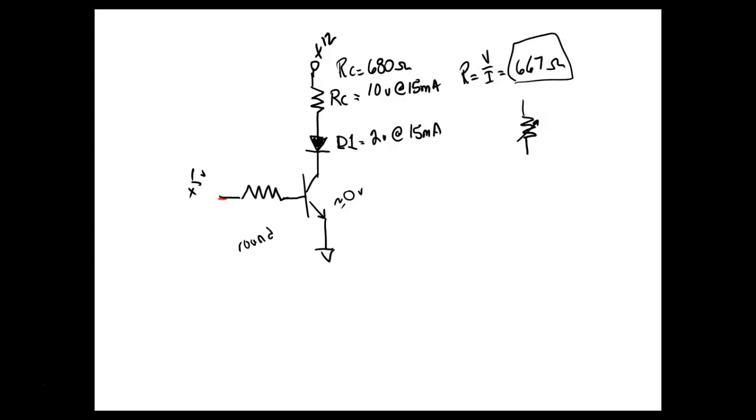Make sure I get the right watt. What are the three things resistors are rated in? Tolerance, watts, and ohms. So we're not concerned with the tolerance here, right? We're definitely concerned about the R value, so we better calculate the wattage rating of that thing.